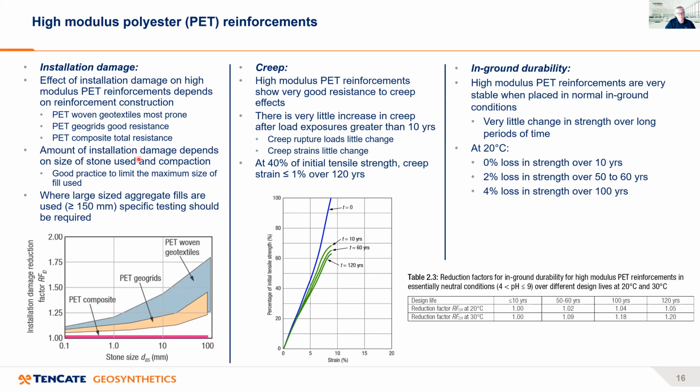So you have total installation damage resistance. So it depends, but also look here, the amount of damage done also depends on the size of the stone. As the size of the stone gets bigger, you can do more damage to it. And so this is why for a lot of reinforced soil structures, it's a good idea to try and limit the maximum size of the type of fill that you're using against the reinforcement.